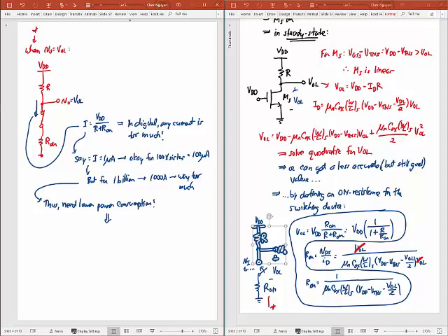And the solution to that is CMOS. That's different from what I just talked about. Here I talked about an MOS with a resistor logic. That is consuming too much power for me. On top of that, I could even complain about that resistor. Remember what I said about resistors? They're too big too. They take up too much area.